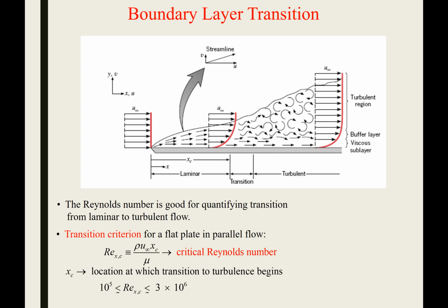That means prior to the flow reaching that critical point, it's going to be laminar. And then after that, it's going to be turbulent. So even for the same physical system at steady state, you could have one region of your system that's laminar and another region that is turbulent. And that's going to drastically affect the heat transfer characteristics.